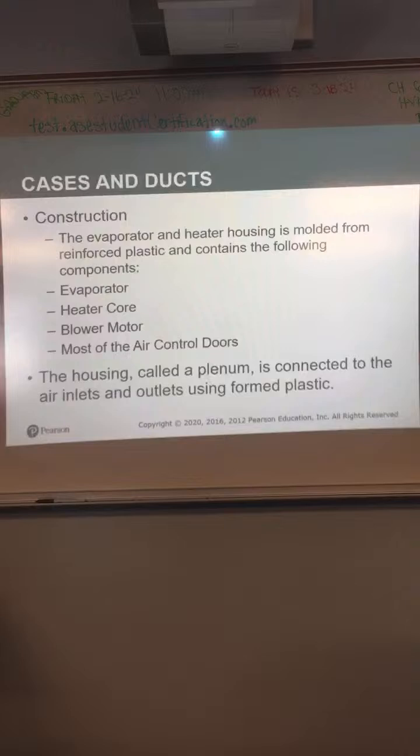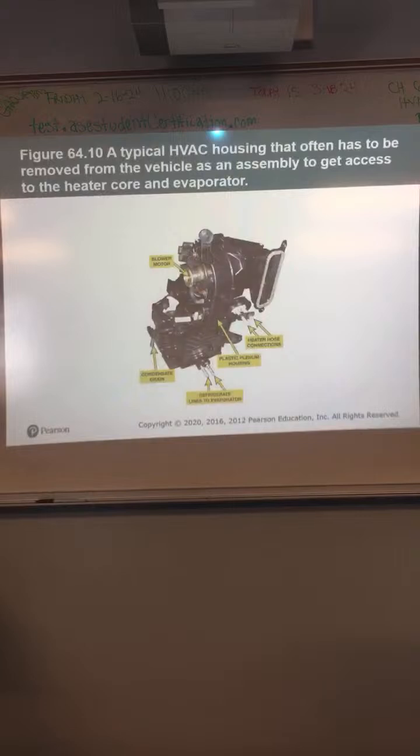Okay, cases and ducts. Evaporator and heater housing is molded from reinforced plastic, contains your evaporator, heater core, blower motor, and the air control doors. Housing is called a plenum, connected to inlets and outlets using formed plastic. That's an actual picture of one.